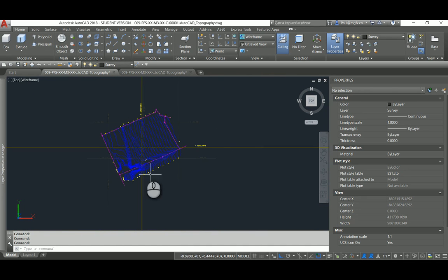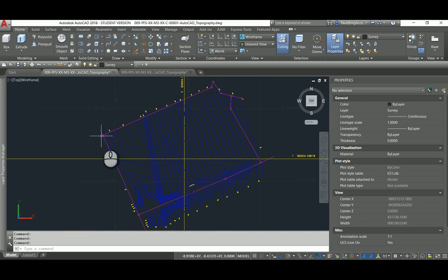The reason for that is often one only has a surveyor diagram which would give one the corner points of the property, but there would be no information with regards to the contours that you can see running across the drawing over here. So typically these contours would not be there. One would then have to go and contract a surveyor, perhaps use a drone with photogrammetry or even a laser scan to help build up that surface.